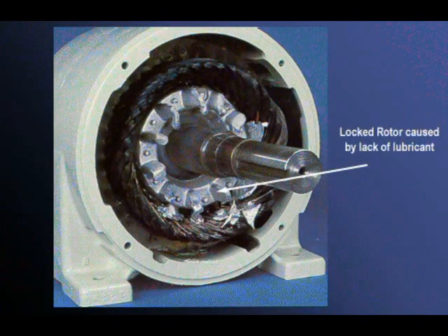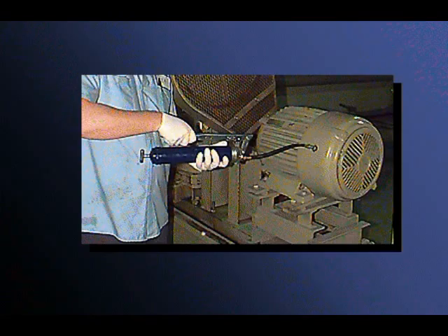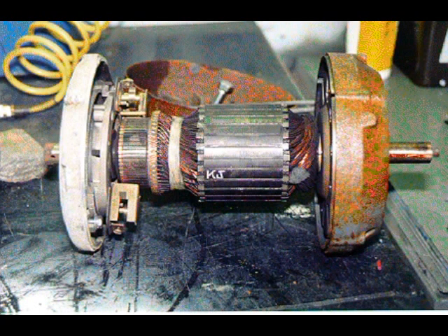Friction causes wear in all moving parts, and lubrication is needed to reduce this friction. It is very important that manufacturers' lubrication instructions are strictly followed. Too much grease or oil should not be added, as this in itself can cause friction and generate heat. Furthermore, an excessive amount of grease may penetrate the motor windings.